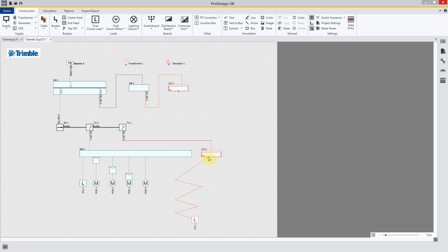The software doesn't care how you get from point A to point B as part of your connection. It only cares about the network. There's nothing to stop you creating a drawing as wacky looking as this. However, once you start drawing with lots and lots of cables, it does become a bit of a mess. So we would recommend that you always leave orthogonal lines set.